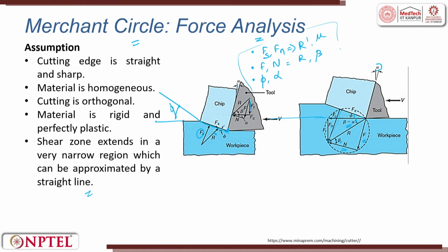So, these are the forces which are there. Now, from this I will have to find out what is the cutting force which is required while machining, right. So, that is the cutting force, Fc, and the thrust force which comes because of this is Ft. So, now I have introduced Fc and Ft.